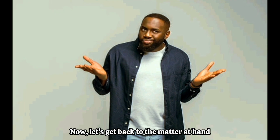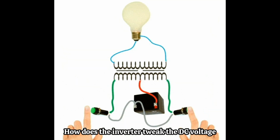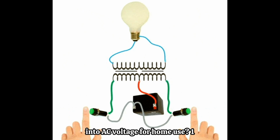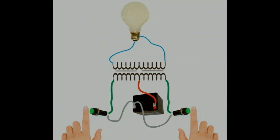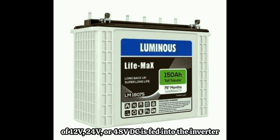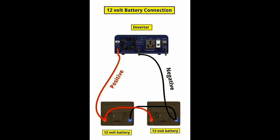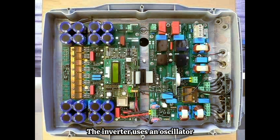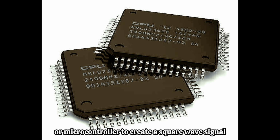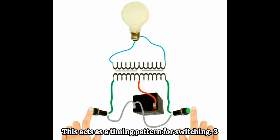Now let's get back to the matter at hand. How does the inverter tweak the DC voltage into AC voltage for home use? 1. A battery or solar panel of 12V, 24V, or 48V DC is fed into the inverter as the input source. 2. The inverter uses an oscillator or microcontroller to create a square wave signal. This acts as a timing pattern for switching.